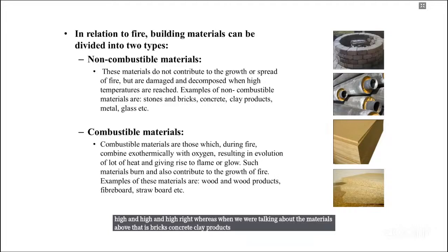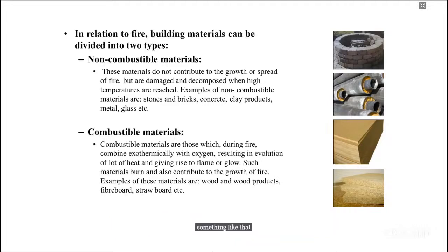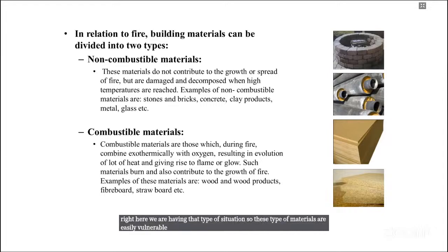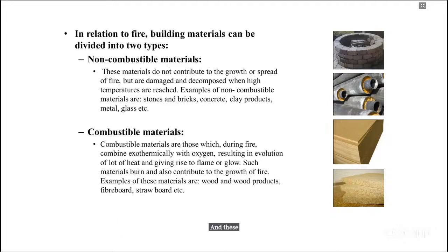Whereas when we were talking about the materials above, that is bricks, concrete, clay products, metal, glass, we were not finding that type of oxygen or something like that which can give the heat and a flame, right? Here we are having that type of situation. So these types of materials are easily burnable, they burn and also contribute to the growth of fire. And these materials include wood products, fireboard, strawboard, etc.